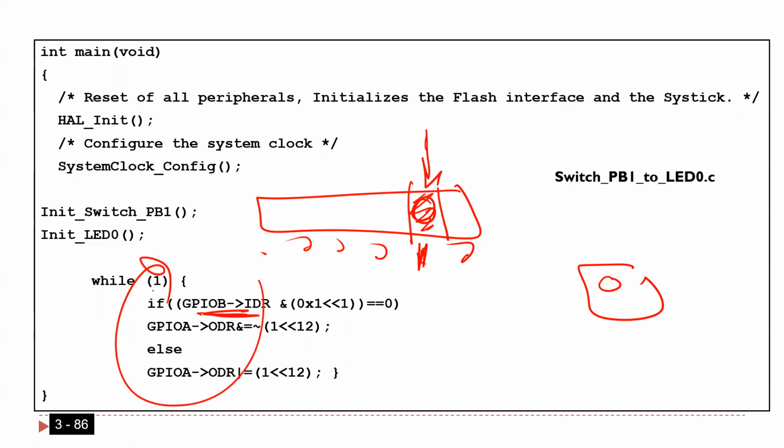And I'm gonna make it loop. Why am I making it loop? So that at any time, it's not only one time, it's inside the loop. At any time you change the status of the switch, what I'm doing here is reflecting, I'm echoing. So here I echo the status of the switch to the LED. If the switch is in one position, the LED is on. Always. If it's in the other position, it's going to be one position on, one position off. Any questions?